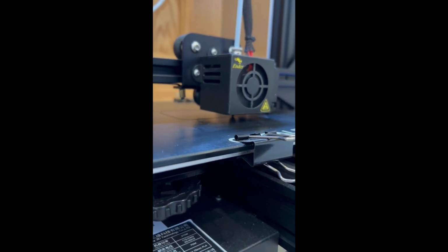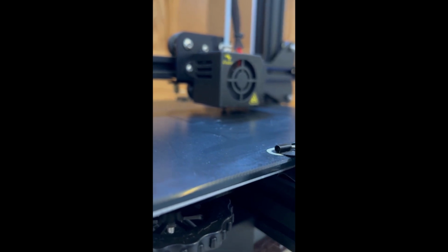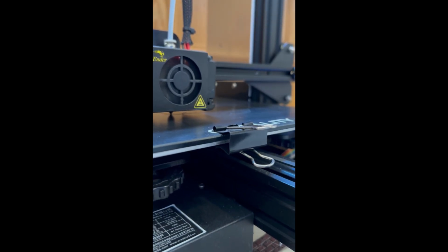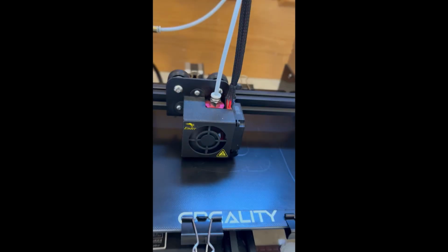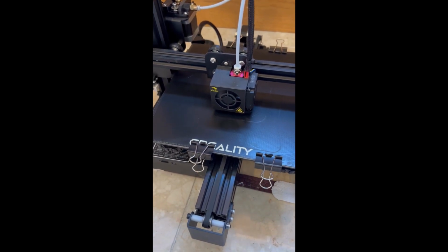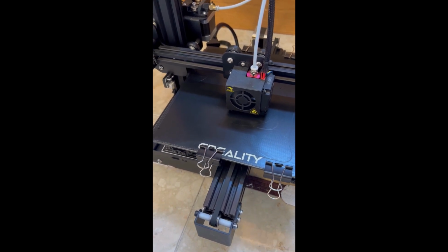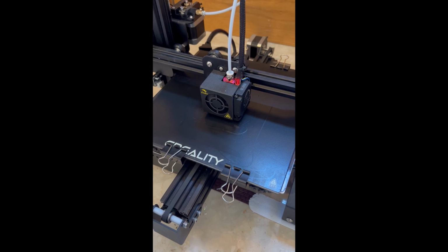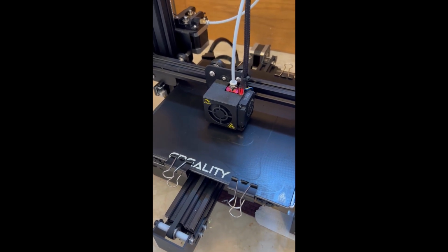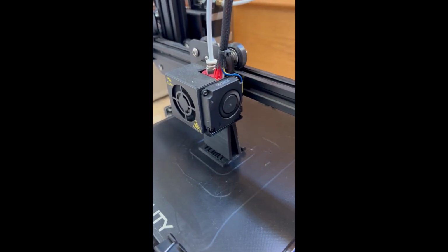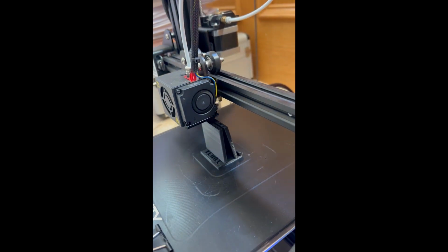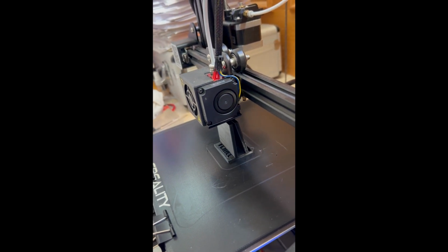So there are other tutorials out there that can tell you step by step how to do this. But basically what I like to do is I like to use a little skirt around the printing area, and then inside this little skirt. That skirt is actually kind of like a small little berm or dike. What that does is it prevents cool air from coming in and prematurely shrinking your print, and that will prevent warp. So it actually has a function. You can kind of see that little square around it, and that serves a function.